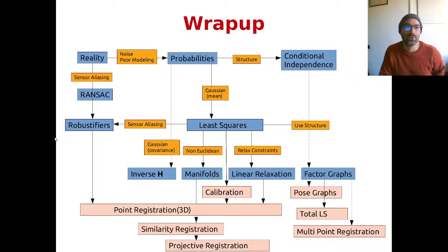If we have few wrong data associations, and if we have an initial guess, then we could deal with them by using robust kernels that basically neglect those measurements that have a high error, assuming that most of the good measurements will have a small error. And this is done within every individual iteration of our least squares machinery. If we are in a situation which is a little bit worse, we could use some sample-based consensus, that is RANSAC, that we have seen two lessons ago, of which I will talk in the next slide.